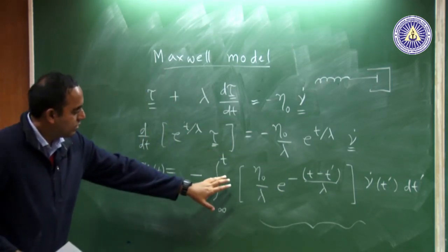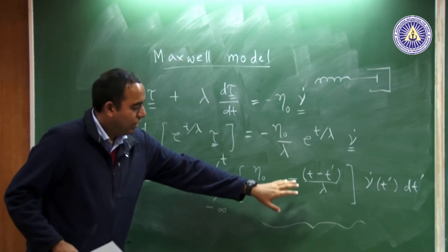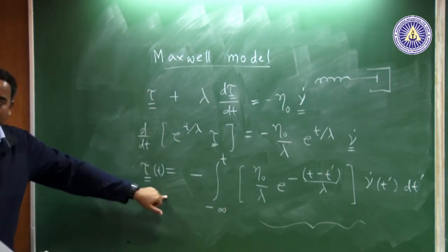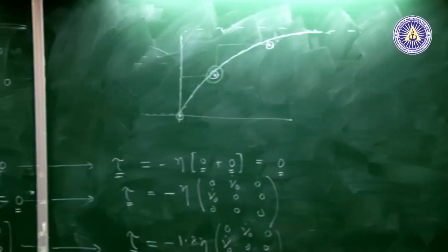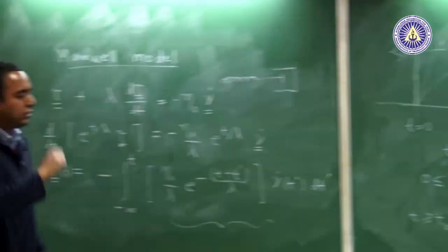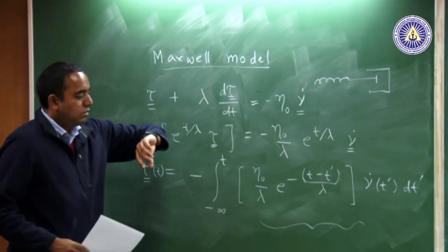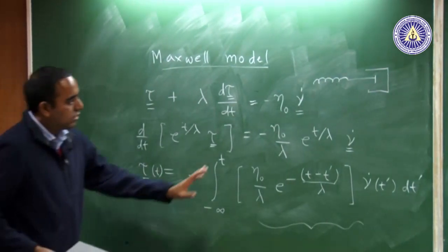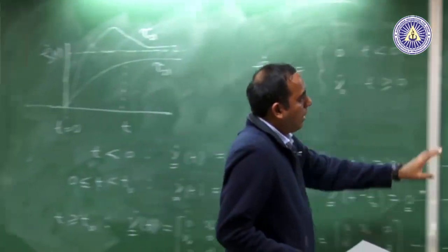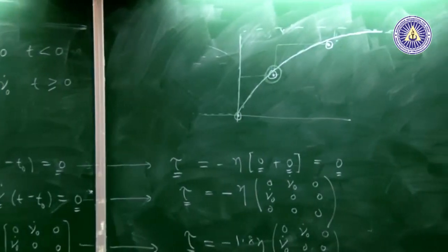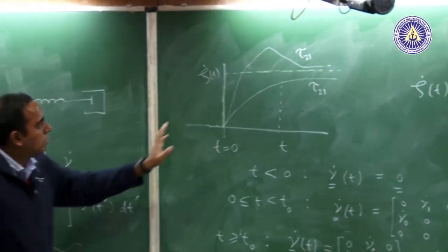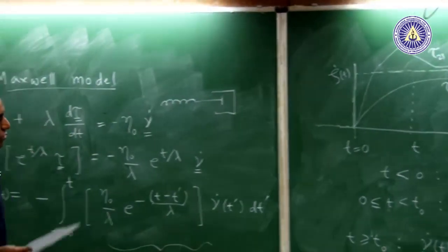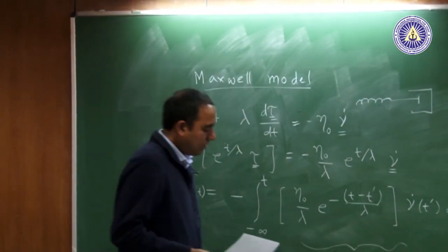So, essentially, if you look at it this way, it is just a constitutive model with infinite memory terms, which actually predicts this sort of continuous monotonic approach towards the final steady state value. So, I will probably stop here. So, this is the point where the memory fluids come in, and with the memory fluid what we can achieve is to explain this sort of graphs, not the overshoots, but this sort of graphs which monotonically go towards the steady state.